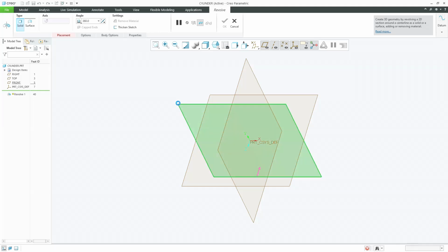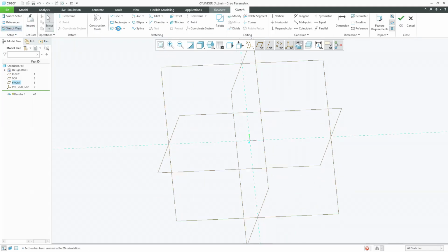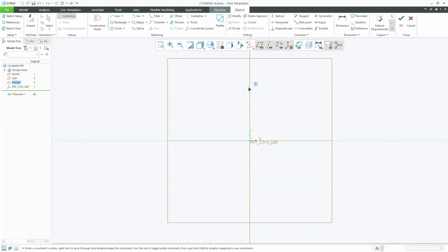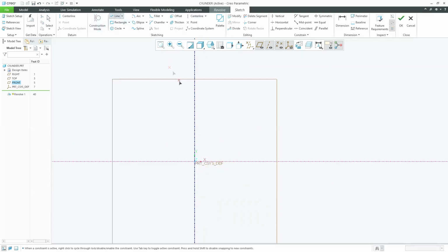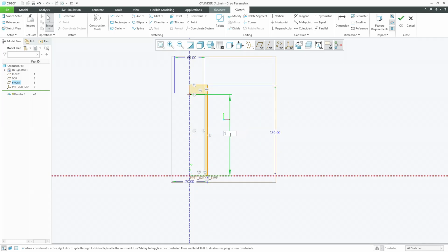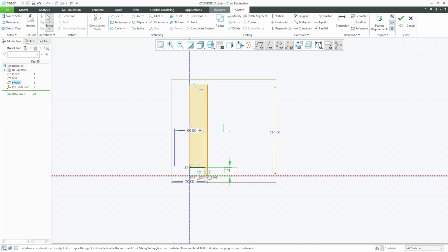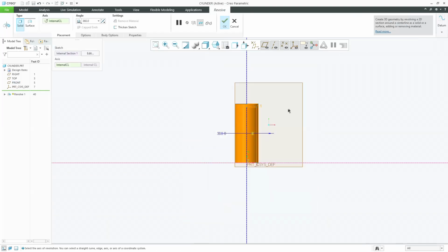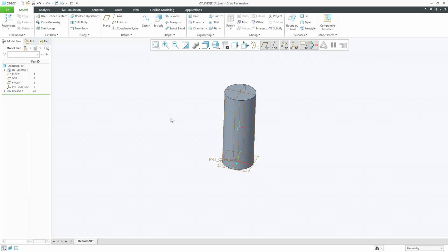Selecting the revolve, click on the front plane, moving to sketch view, and I click on the center line, axis line on the vertical and center line for the horizontal. So here I'm going to have a cylinder construction where the internal diameter of the cylinder matches the external diameter of the piston. So the value of this internal diameter is 60 and the external diameter is considering as 70. I'm going to have this length as 180 and the internal thickness as 170. Sorry, 170. Just click OK here. So a cylinder kind of a structure I have created.